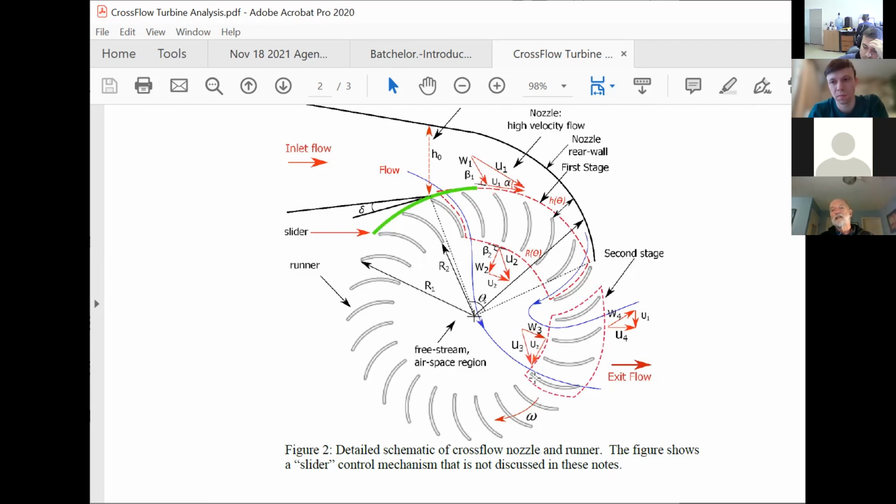So we actually got quite a nasty shock when we went through the whole process of doing a lot of CFD simulations with varying numbers of blades, et cetera, to try and push the efficiency high into the 90s. And then we found that our most efficient turbines were cavitating.